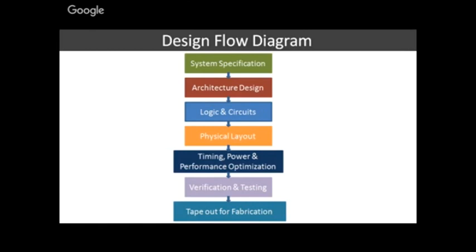In floor planning, we devise the area, and determine the dimensions of the blocks you are using and the positioning of your IO pads or pins on the chip. This is a rough estimate of your chip design, where we put this instance and where we put other instances. After this, we do the placement. Placement is the optimization of floor planning. Here we deal with the actual size of your macros and make the interconnections between them. Further, we do the routing. Routing is necessary to make the interconnections, and the wire length of your interconnections should be small, so that the effect of parasitic components such as resistance and capacitance becomes lesser.